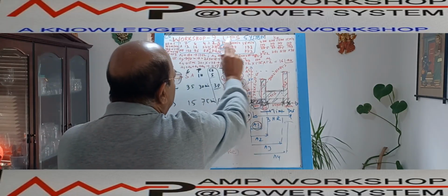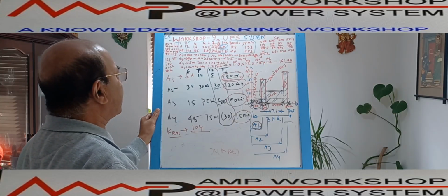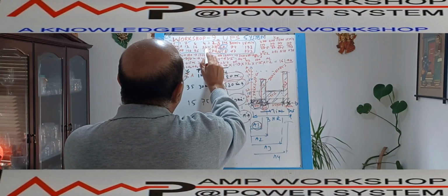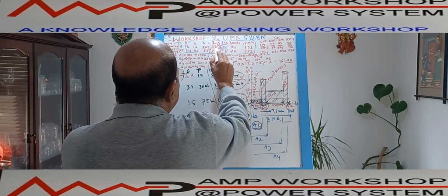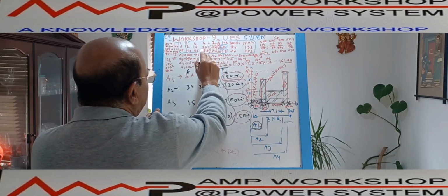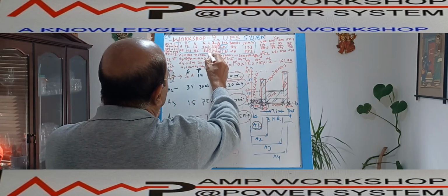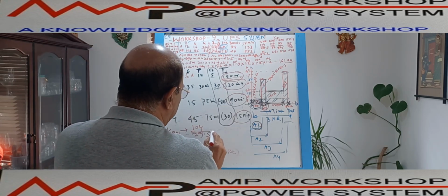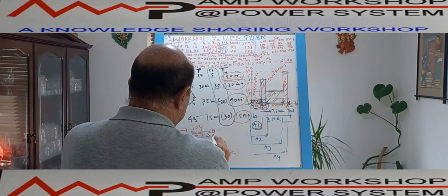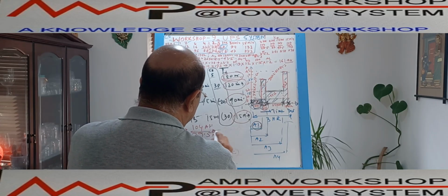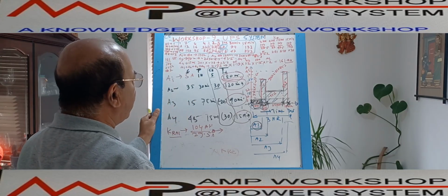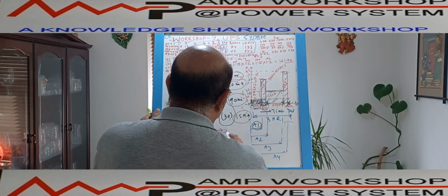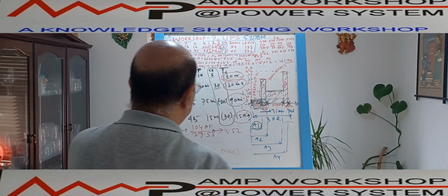Now if you go to the battery characteristics, for 3 hours how much current can it deliver? You see here, 4 hours it can deliver 22 ampere. For 2 hours it is 37 ampere. So 3 hours will be in between, that is 29.5 ampere, which I have calculated. So it is 29.5 ampere, and this is the ampere hour capacity. This will give you the factor KR A1. How much is it coming? It is coming 3.52.